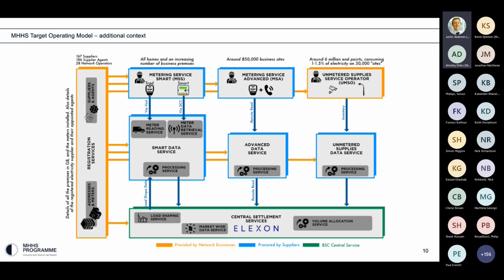Okay, next question. Will the same correction factor be applied to all import and export factors equally, or will there be any differences to account for portfolio type of suppliers? For every settlement period, 2 correction factors will be calculated, one specifically for import sites and one specifically for export sites. What's interesting about them is that they fall about 1. So if it was 1.1 for import, it would be 0.9 for export, and vice versa.